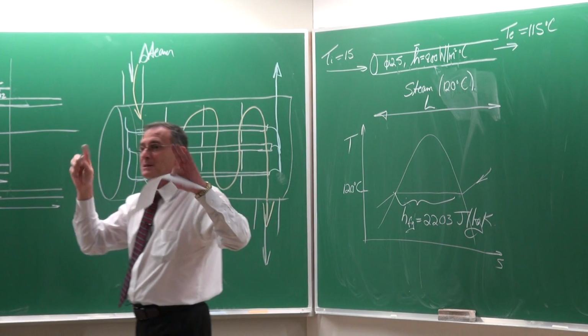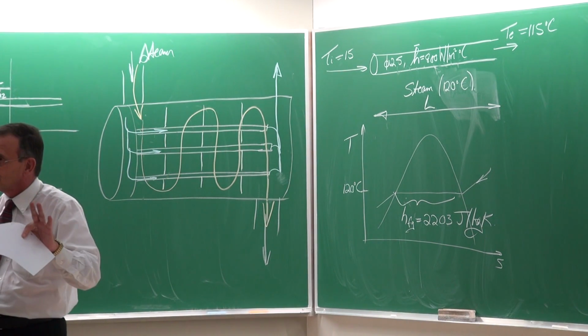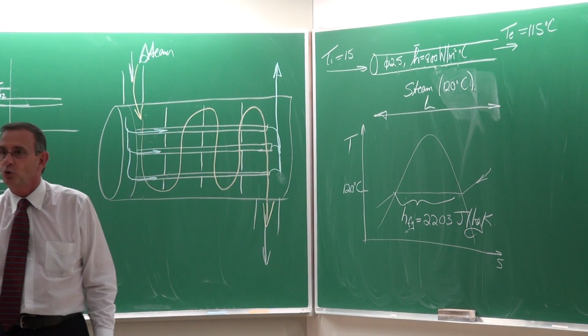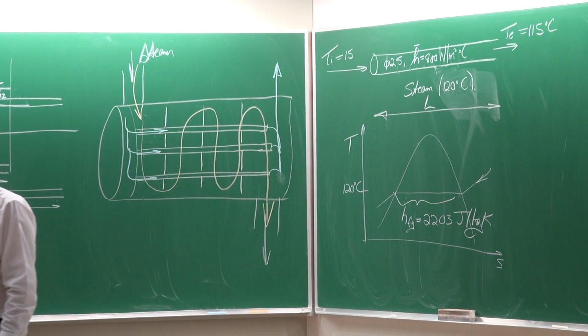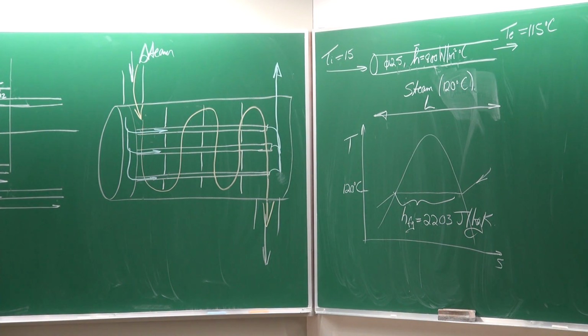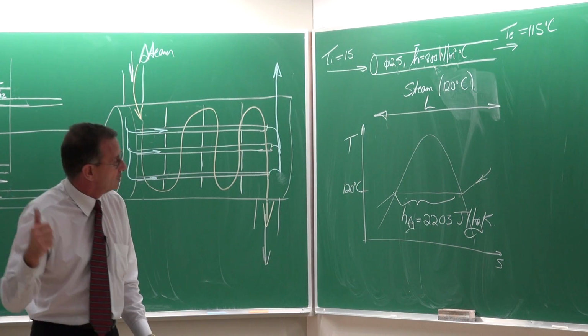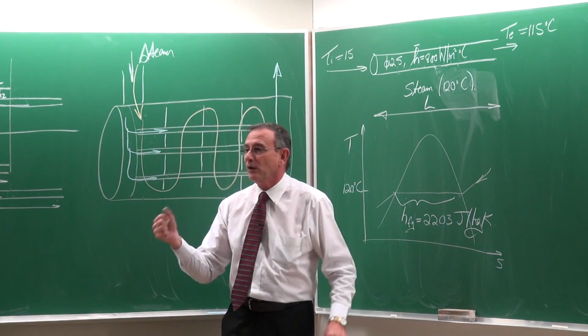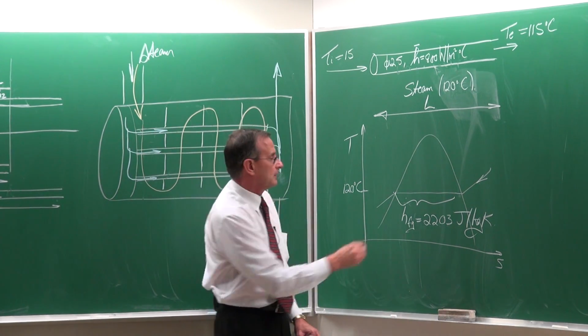While that happens, the temperature remains constant. And that is a very important thing for us to work with if we design heat exchangers, if you can have one of the streams where the temperature does not change. And that you can only get with condensation and with boiling and evaporation.